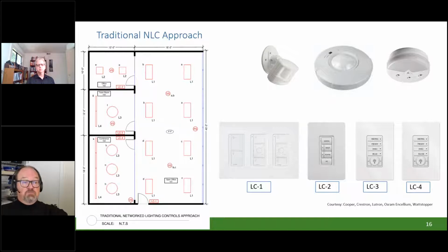In specialty areas like corridors and stairwells, they can come on to full light output, but in some place like this, they could come on to 50% light output. With the vacancy sensor, as I walk in the door, I have to push the on button for all or whatever control zones I want to have illuminated. Duane, does that cover it, or am I missing something more?